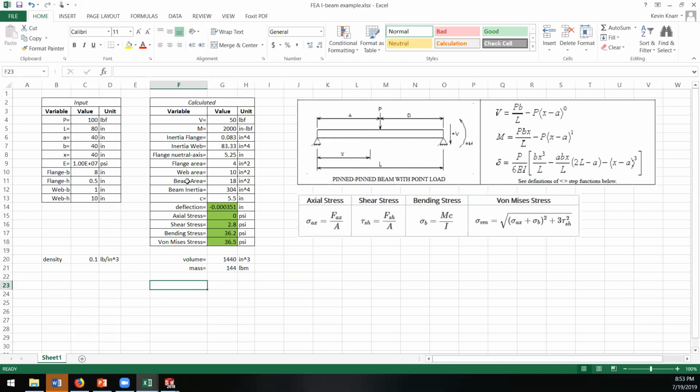Where is it? You don't need it for this, but it's deflection. Oh no, it's up there on the left. It's somewhere here. 10 MSI, it's 10. It's like aluminum. That is a material I use, so I put the material property in, and I made sure this matched the SolidWorks. That's the other thing: you could get this from a textbook and then choose a material in SolidWorks, and SolidWorks assumed the modulus was like 9.9 instead of 10. You'll get slightly different answers.